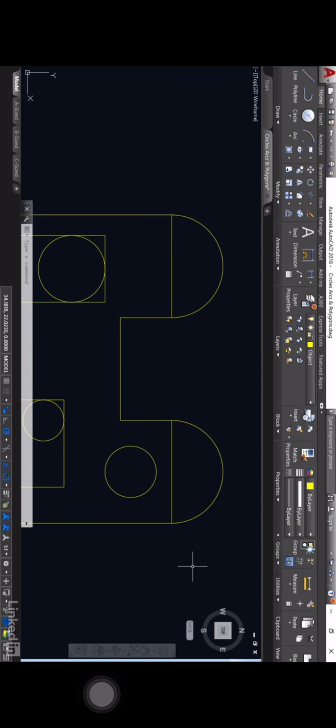Last but not least, let's have a little look at the polygon command. Again, that's on the draw panel, and it's here with rectangle. Click on the flyout and go to polygon and come into the drawing area. Now you can specify any number of sides between 3 all the way up to 1024 sides with the polygon command. Now, I'm not going to go for a 1024 sided polygon. Not really effective, and it won't really show what I want to show you.